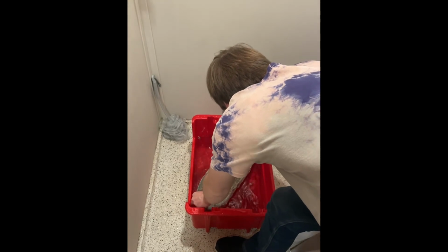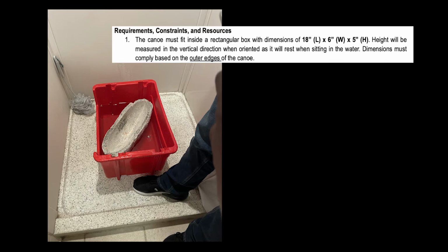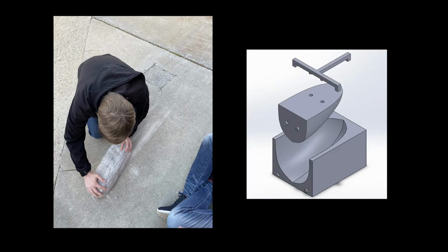We put it in the water, and it floated. We were happy, but we had forgotten one thing: our constraints. We had to ensure that our width was 6 inches maximum, but our width was slightly too large. So what did we have to do? We had to scrape it. Scraping down the concrete not only helped us to get it into the proper dimensions for Fed, but also to get it into the correct concave canoe shape that we wanted.